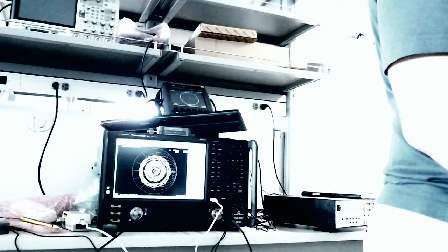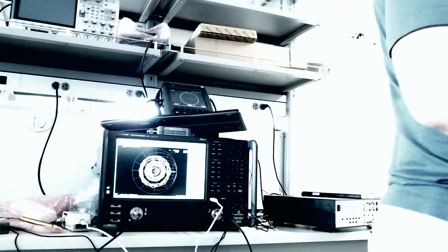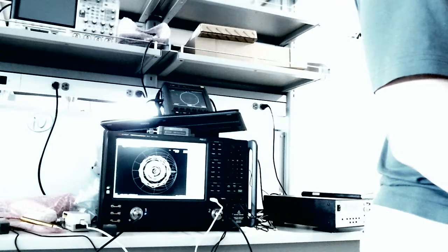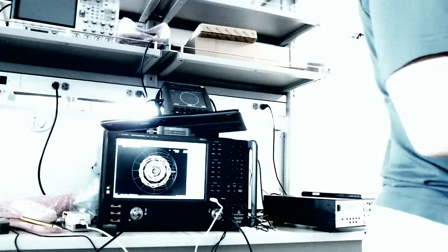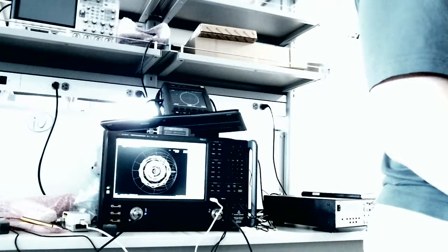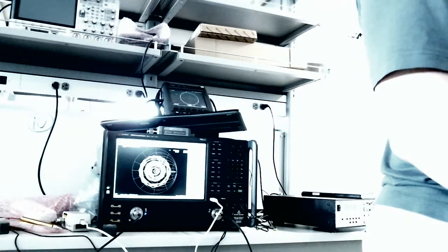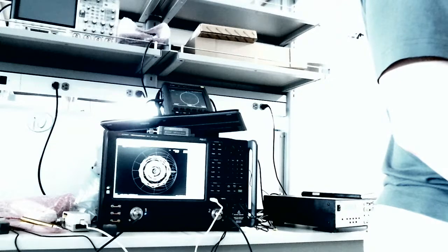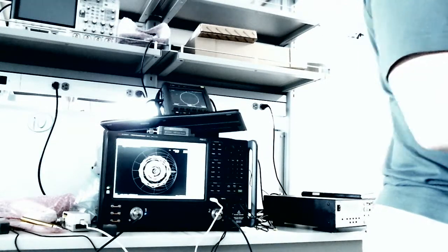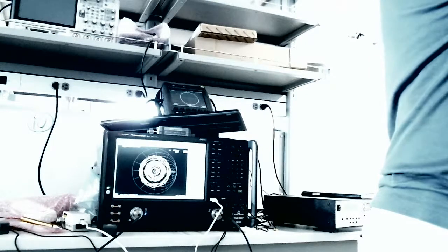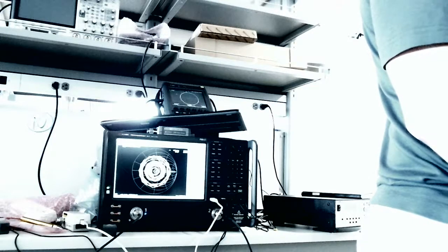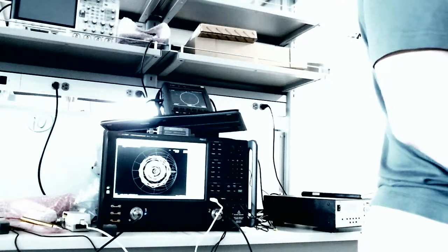And as long as it's not coated in an insulating material, you give them the right amount of feed line, and then what you say is, okay, they measure this impedance. If they know what the length of this is, they can also know how far it's been moved on the Smith chart, so they can extract what the impedance is over there. And they can physically measure that. That's not a big deal.